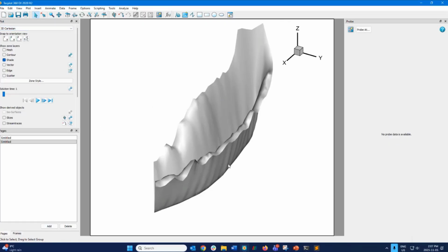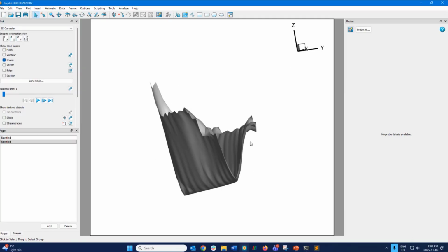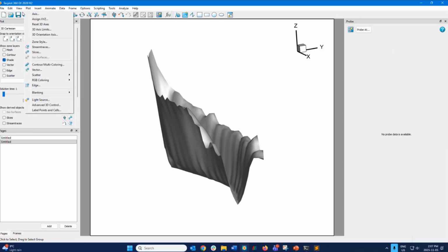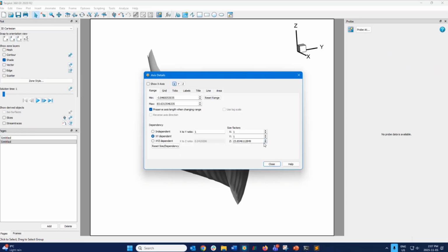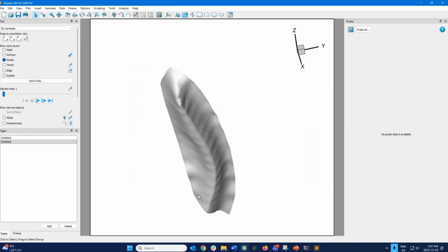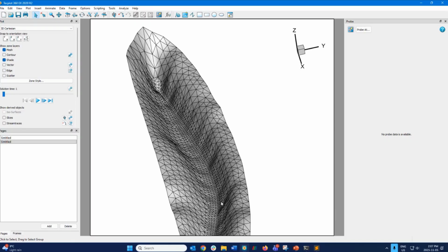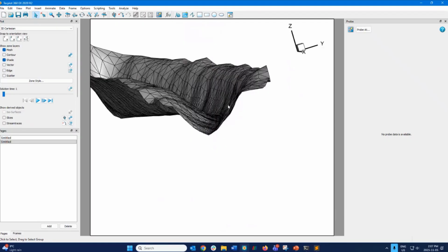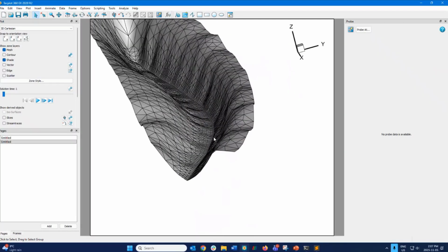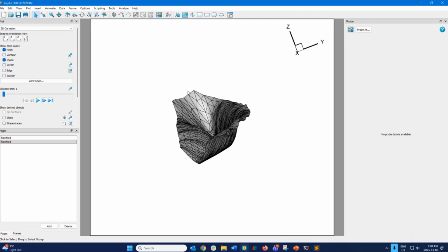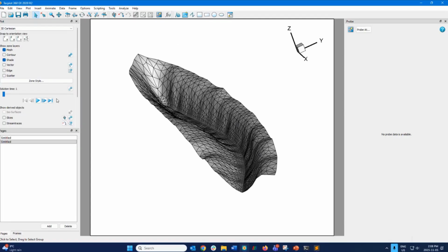We can display this in 3D Cartesian space. So the surface domain, the vertical exaggeration here is really high. You can maybe change that a little bit. But it's a pseudo 3-dimensional zone, right? So every element, every triangle, every tile in this mesh is 2-dimensional, but altogether they create a quasi 3-dimensional model domain. And this is just draped on top of the porous medium domain.